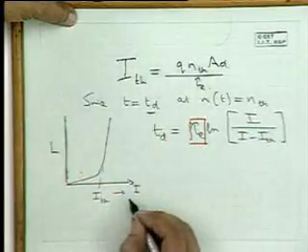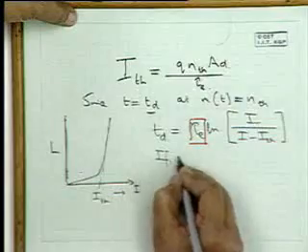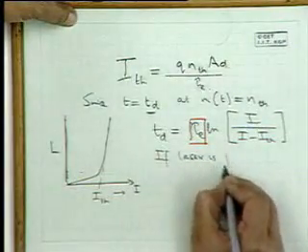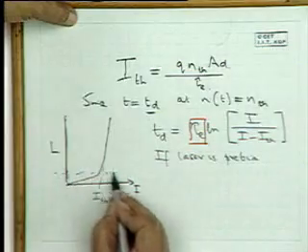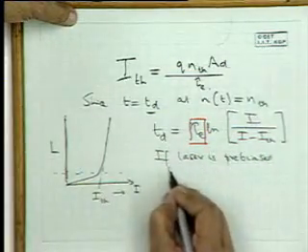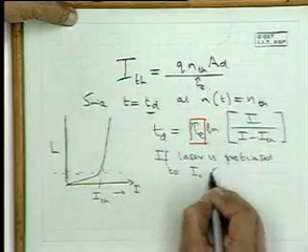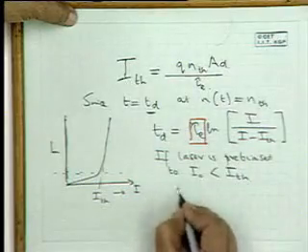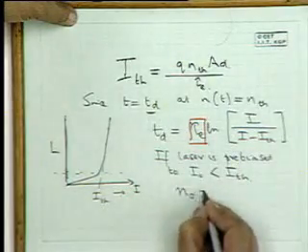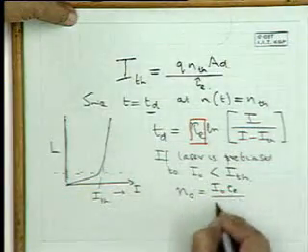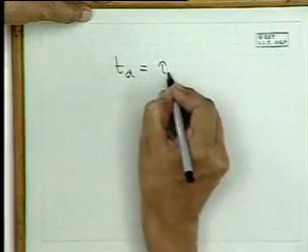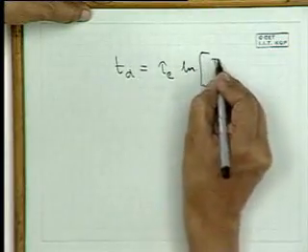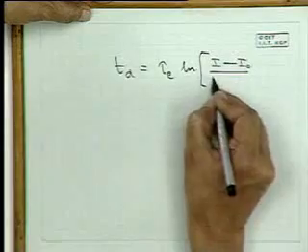So we want to decrease t_D. How can we do that? Suppose the laser is pre-biased, that means, instead of switching on right from zero, suppose we pre-bias it to a current I0 just less than I_th, and the initial condition for n corresponding to I0 is n0 equal to I0 tau e by A q d. Then instead of going from 0 to I_th, t_D is tau e, exactly the same expression, but I minus I0 over I minus I_th.